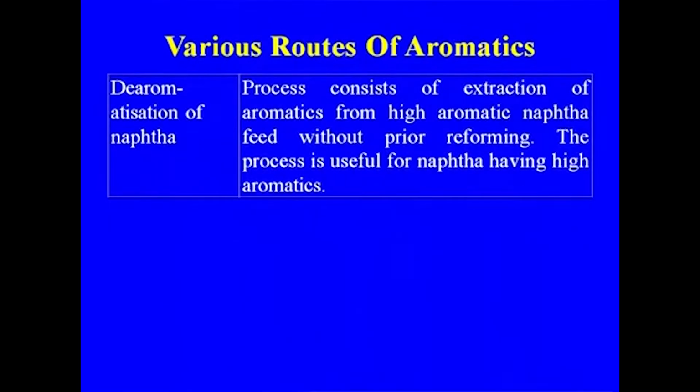De-aromatization of naphtha: as I told you, some naphtha is very rich in aromatics. So instead of going for catalytic reforming, this process involves the extraction of aromatics from high-aromatic naphtha feed without prior refining, because now a number of solvents are available, and from that we are able to extract the aromatics from the naphtha. Here we do not need any further reforming process for making the aromatics. The process is useful for naphtha having high aromatics.